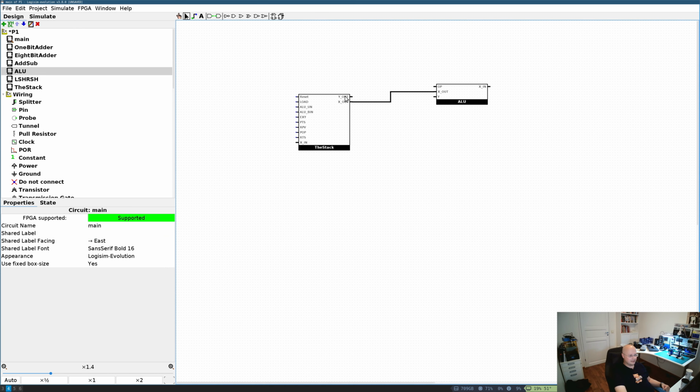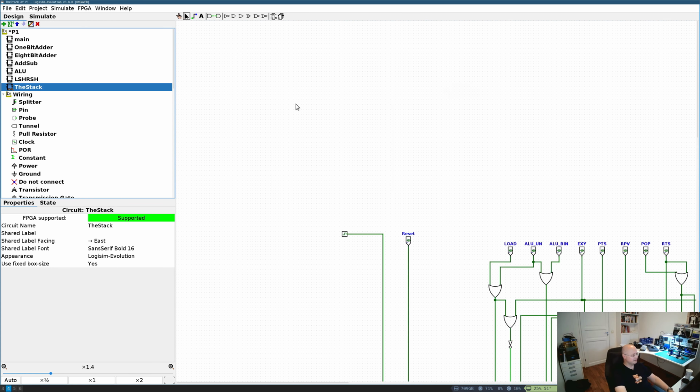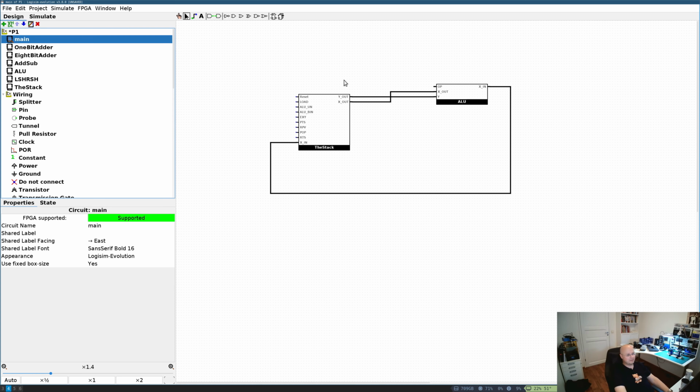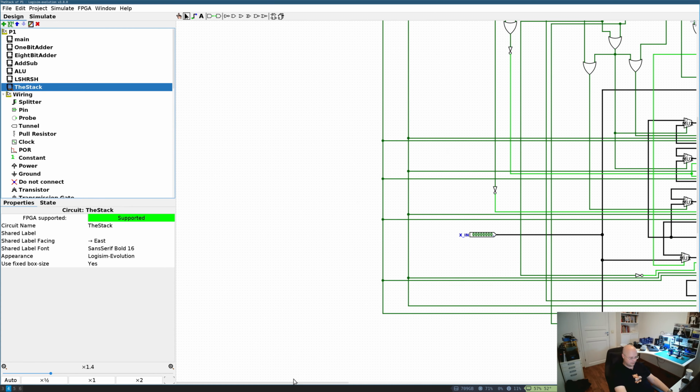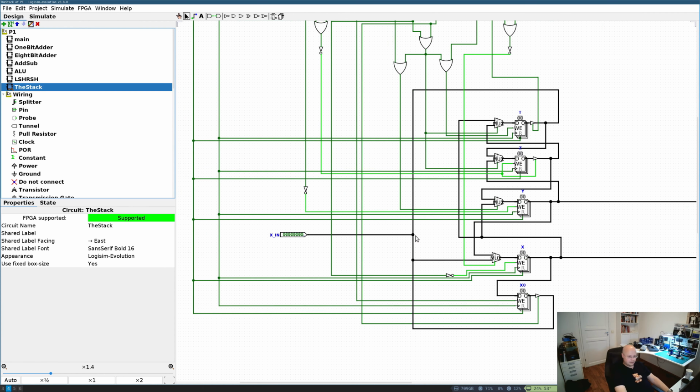But you remember that in the stack the X is the same register. So when you make, say, a negation or addition, when do you write the X in? When do you store it? You need to wait for this 600 nanoseconds before you store it. And that's why CPUs are limited in clocking. Well, that's not only the reason, but one of the reasons why we are limited in our clocking. The clocking period needs to be at least longer than the longest critical path.